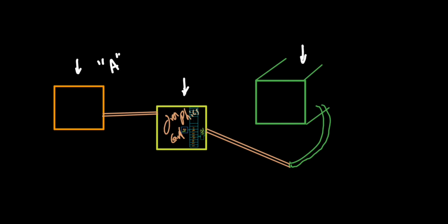The type of monitor that we are talking about has a cable, and inside the cable there are some pins which are connected to the graphics card. One of those pins is called the VDO pin. If the VDO pin is 0, or the low voltage, the monitor wouldn't emit any light and therefore we would see black on the display. If we put the high voltage, or 1, then the monitor would emit light and we would see green. So we say that black is the background color and green is the foreground color.